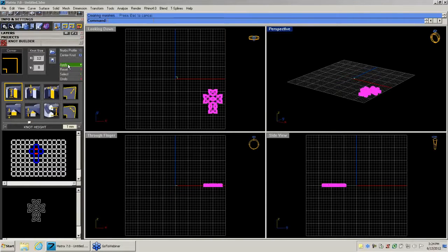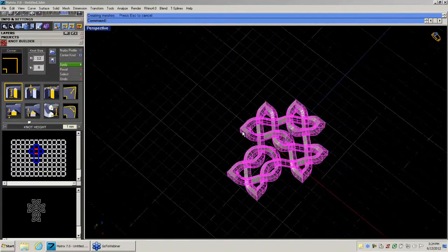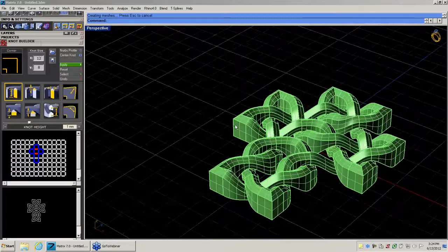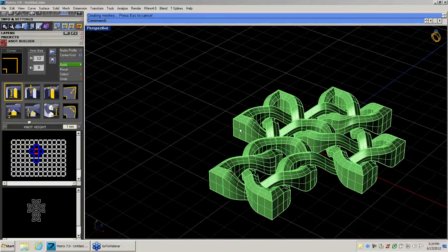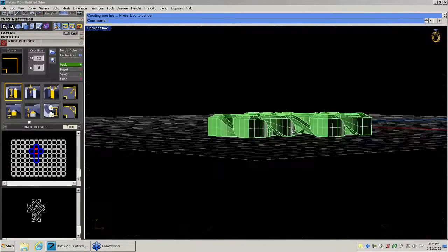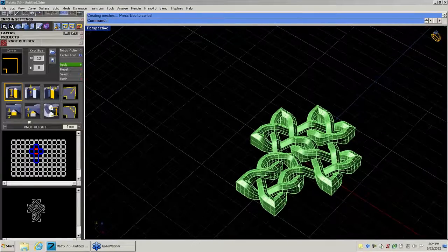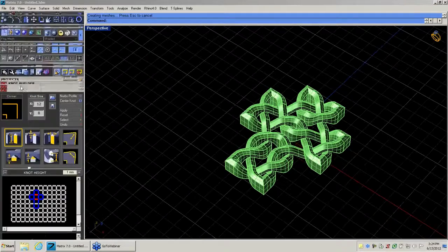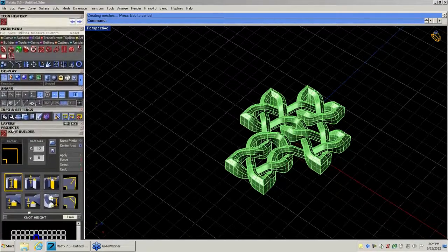Now as you watch this thing draw, if I didn't have this builder, what I would really need to do is I would need to physically go in and create a line that followed this shape all the way around, and then try to determine which one goes up and which one goes down. So what I just did here in a matter of really seconds, this might take you 20 to 30 minutes to draw this Celtic knot the way that I did in a true knot coming off of here like this. And so that's where builders become your friend.